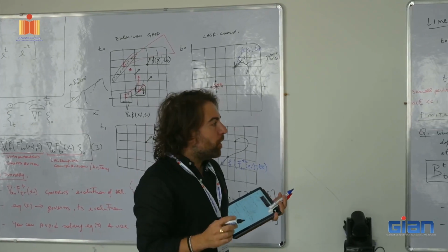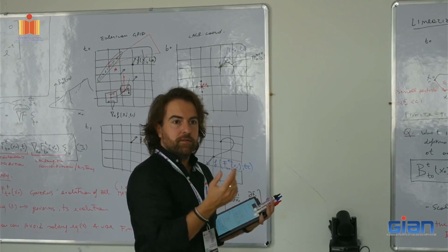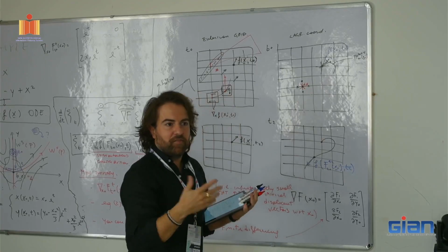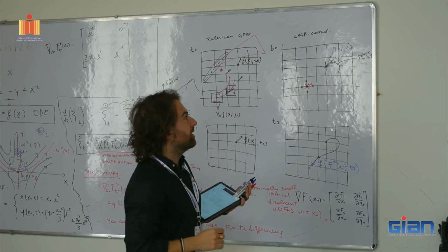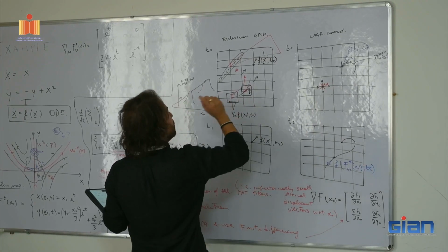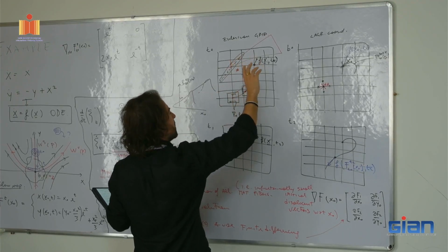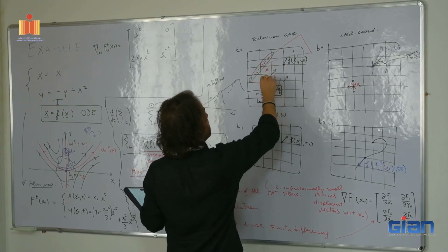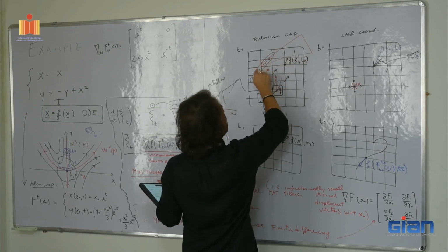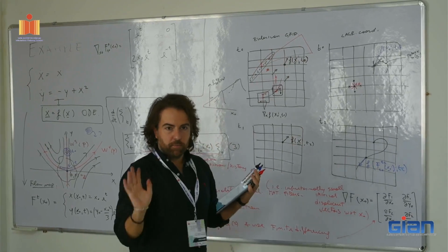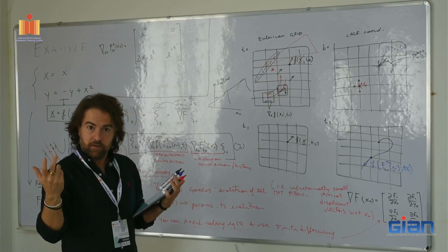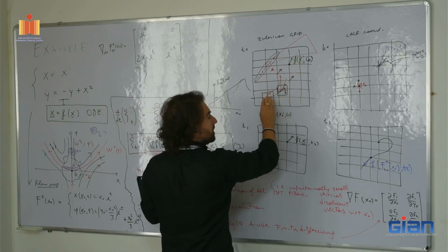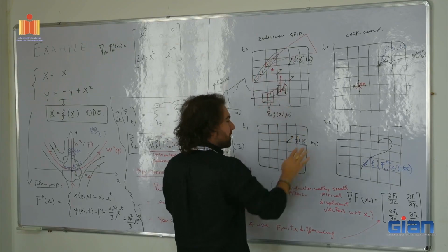The point is that when you have a nonlinear system, depending on what you start sampling, it's going to be a very different alpha, depending on the orientation, etc. However, if you want to say what would be the effective stretching exponent that would achieve this cumulative stretching in this time interval, that's the finite time Lyapunov exponent. It's a generalization of a stretching exponent that takes into account the fact that you are moving along trajectories and sampling different points that have different gradients of velocities, etc.